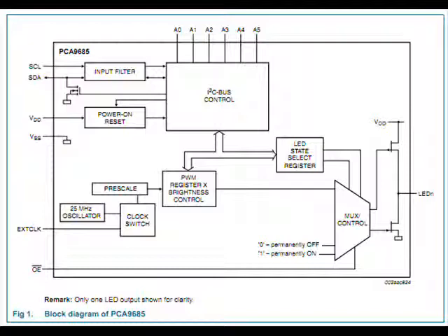But I can have multiple of these 16-channel devices, and they can be slaved together and synchronized by the clock. And as I mentioned previously with the light-dark cycle research, I can bump the clock rates up quite a bit. So there's some really cool things that this PCA9685 allows for.